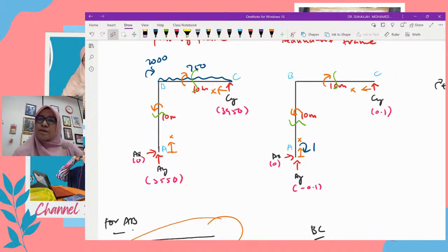We just need the moment equation to get displacement. Once we have displacement, we can substitute into the compatibility equation, solve for the redundant, and from the redundant we can solve the remaining reactions. Once you are clear about the moment equation, everyone can solve this until the end.